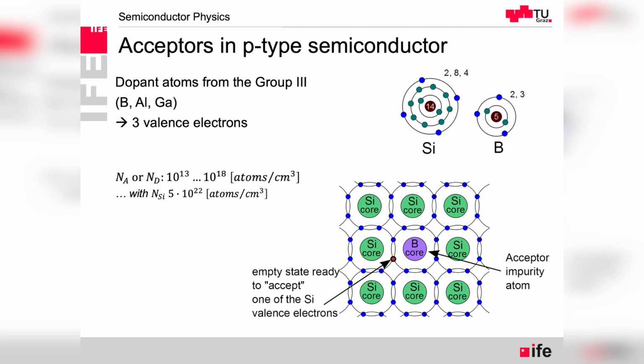The typical values of doping in semiconductors are something like 10 to the power of 13 to 10 to the power of 18. Of course, physically it's not possible to go much higher, because we would have a very compressed material which would not be a crystal. So, maintaining the crystal structure, we can replace atoms reaching a concentration in silicon of 10 to the power of 18.